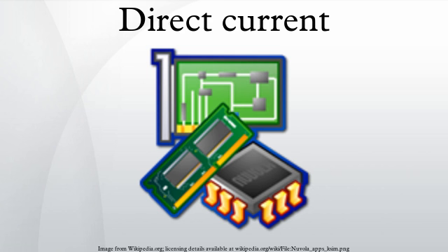The first commercial electric power transmission used direct current. Because of the significant advantages of alternating current over direct current in transforming and transmission, electric power distribution is nearly all alternating current today. In the mid-1950s, high-voltage direct current transmission was developed, and is now an option instead of long-distance high-voltage alternating current systems. For long-distance underseas cables, this is the only technically feasible option.